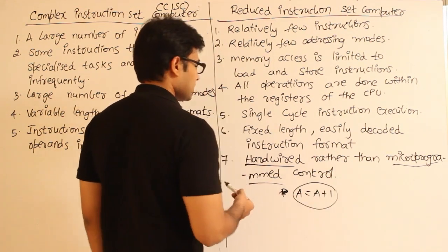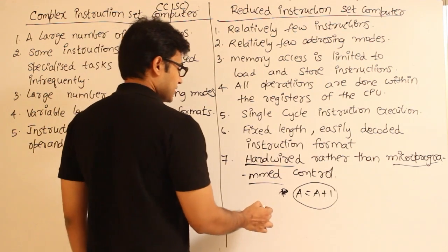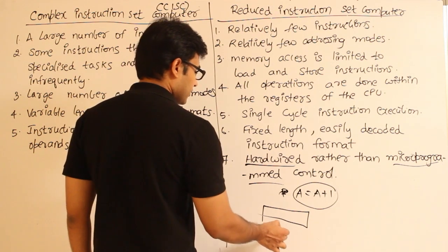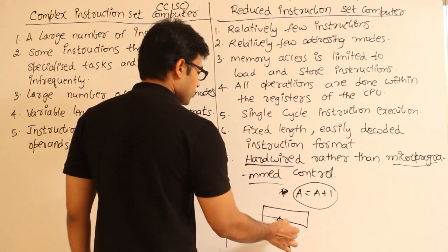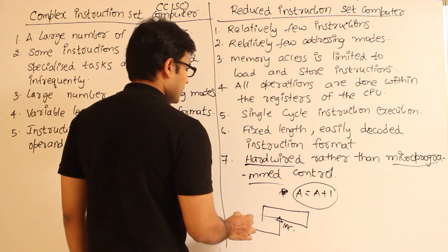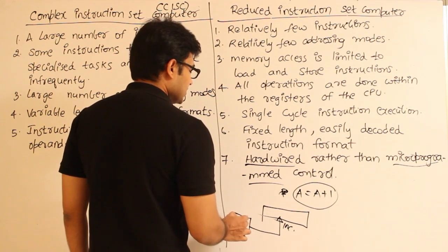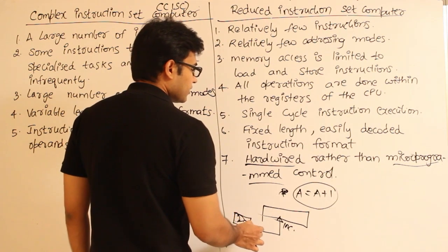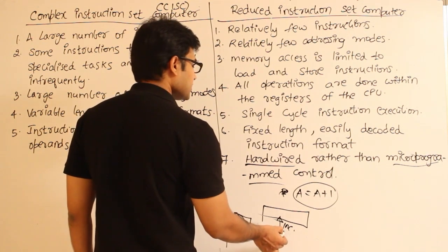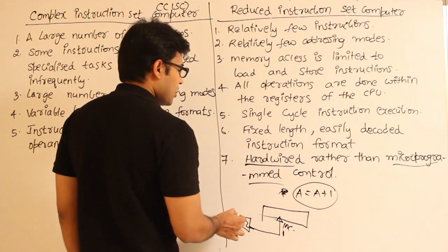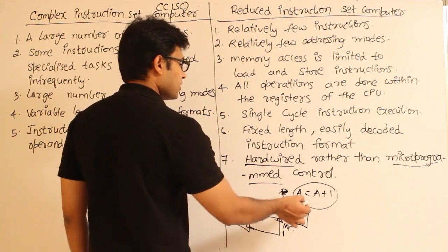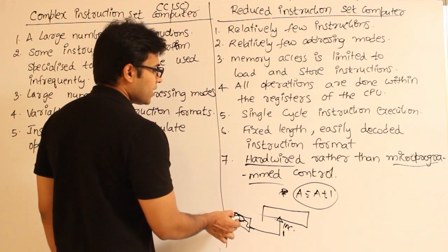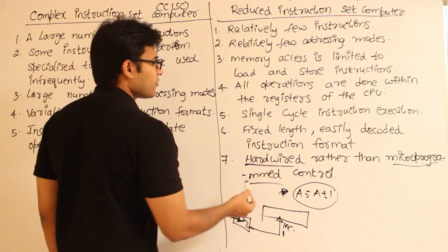In hardware, what happens is, we build a circuit which will directly connect to the increment input of A, and inside this, the gates are going to create a 1, and then that 1 will be given to this, and this will be incremented. How will that 1 be generated? That depends on this instruction. When this instruction is given to this, we design the gates in such a way that 1 will be generated.